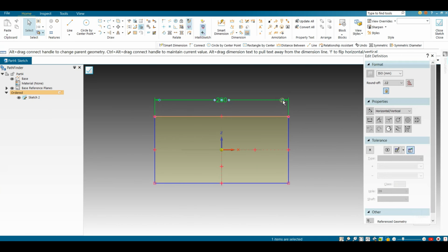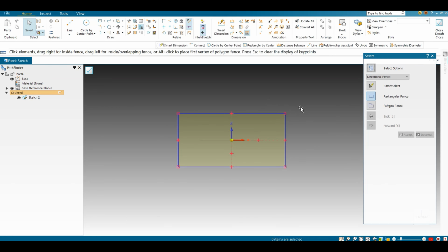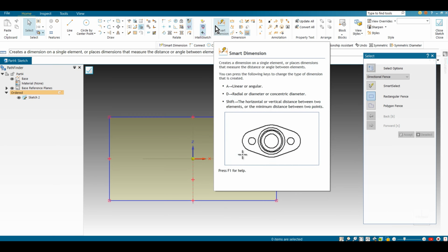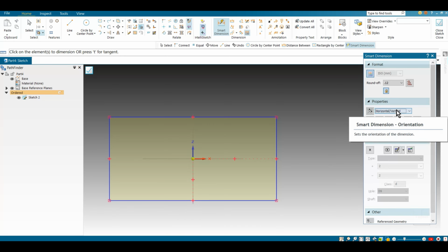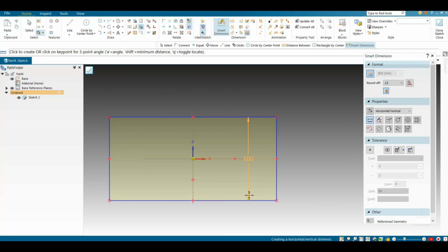If you want to place any dimension to constrain an entity, you just need to go into the smart dimension window in Solid Edge. Here we have various options. When you first use this environment, sometimes users can get confused about what these options are. Today we will explain how to utilize these options to increase the efficiency of your workflow. First is horizontal vertical. If you have two lines and you just want to define the distance between the two, you can utilize this section.